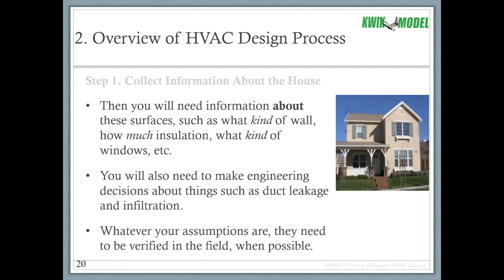Once you know all the physical dimensions of the house, the next thing you need to know is the qualitative stuff. What kind of wall is it? How much insulation is in that wall? What kind of windows? What's the U factor? What's the solar heat gain coefficient? Okay, and then there's some things you're just not going to be able to determine very easily unless you measure them. You're going to have to make some engineering decisions about duct leakage and infiltration unless you can measure those directly. Whatever assumptions you use, they need to be verifiable in the field when possible.